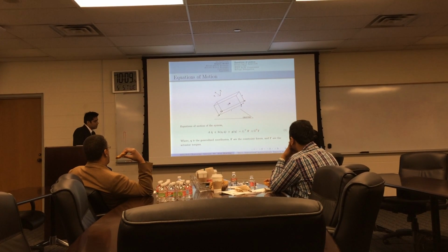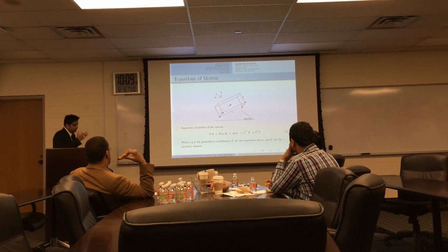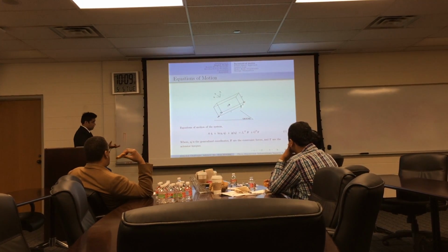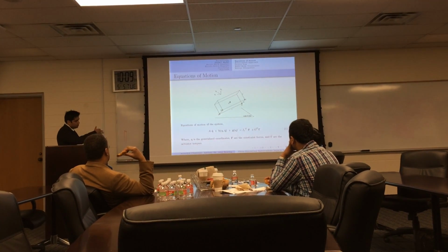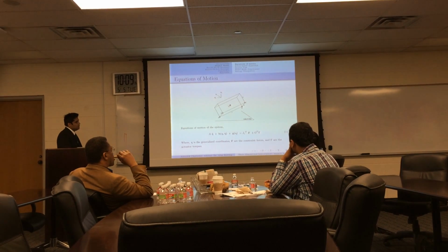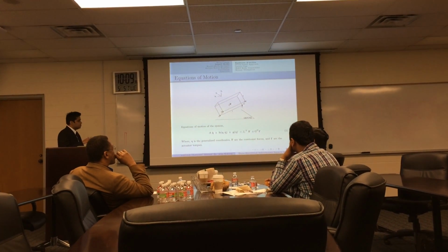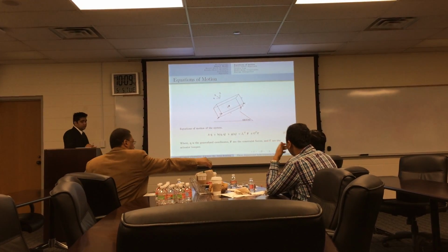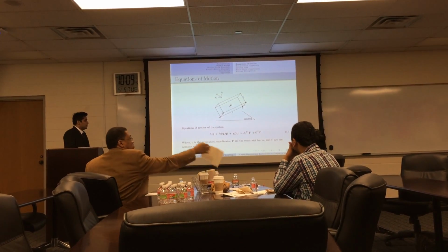JC is the Jacobian matrix that converts these constraint forces, like the contact constraint forces, in terms of the degrees of freedom. And G is a permutation matrix that just selects the appropriate torques for the appropriate degrees of freedom.